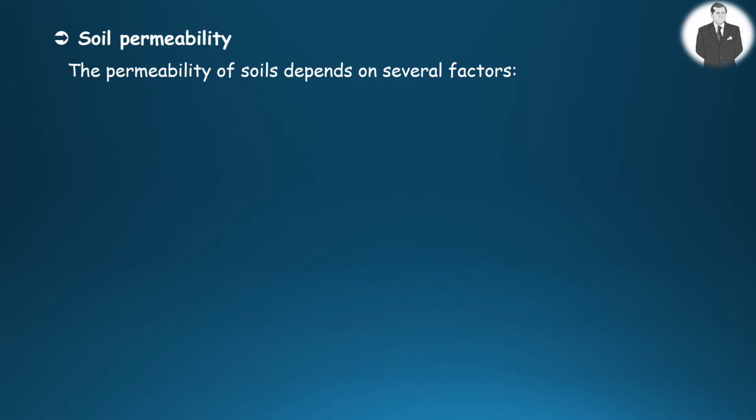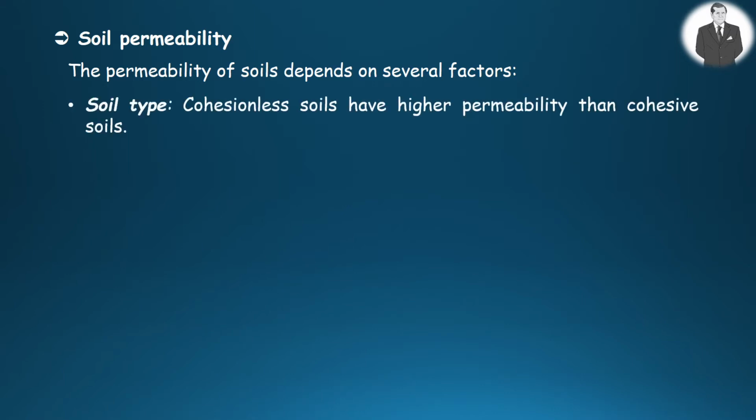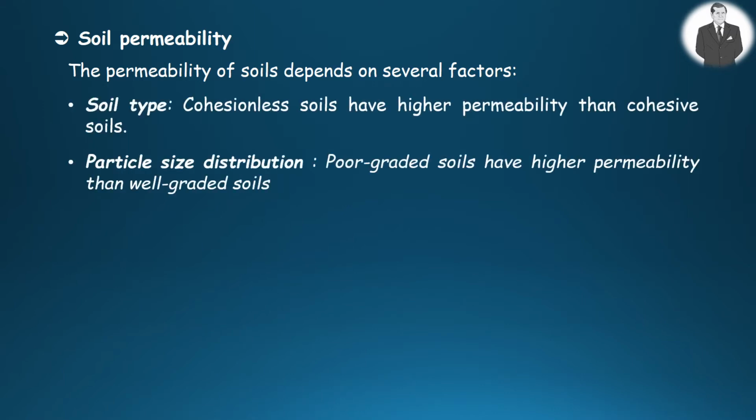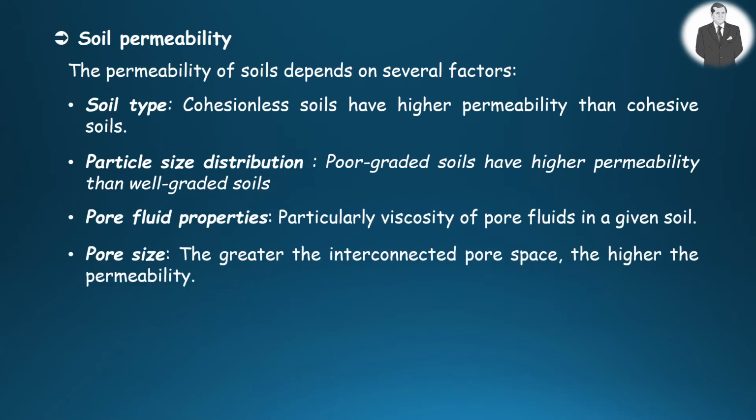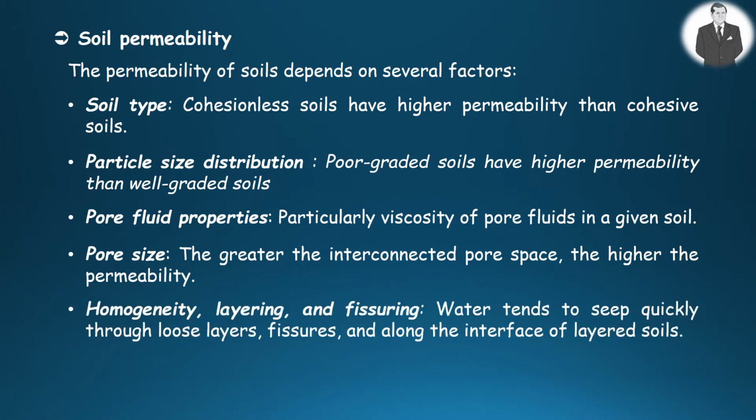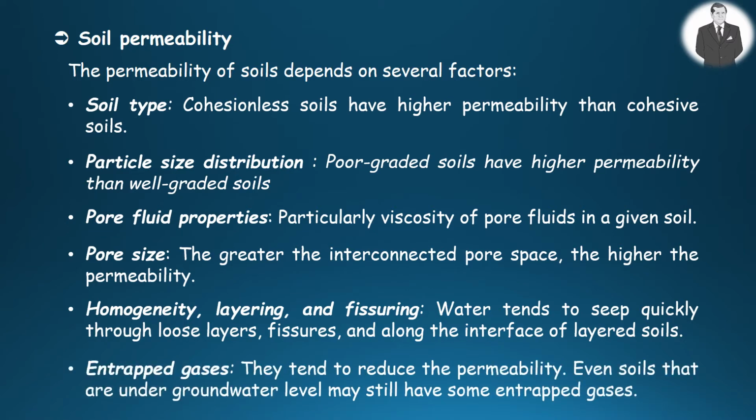The permeability of soils depends on several factors, such as soil type, particle size distribution, pore fluid properties, pore size distribution, homogeneity, layering and fissuring, and entrapped gases. Cohesionless soils have higher permeability than cohesive ones. Poorly graded soils have higher permeability than well-graded soils.